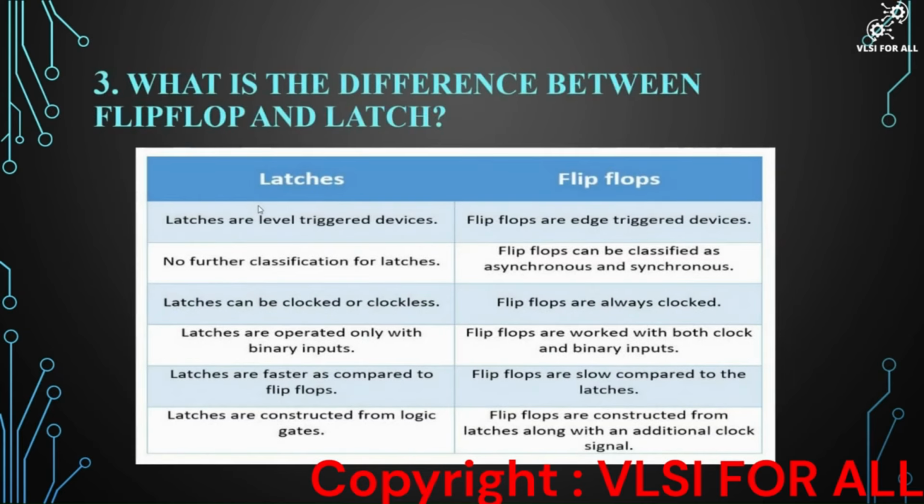Next question. What is the difference between flip-flop and latch? This is the most repeated question in digital interview questions. Right? First of all, what is latch and flip-flop? What is the main difference? The first point is latch is a level triggered device and flip-flop is an edge triggered device.